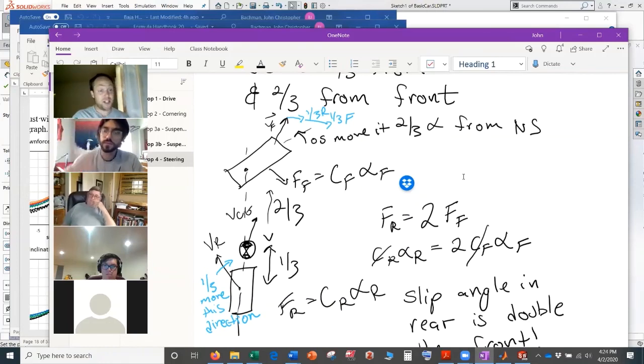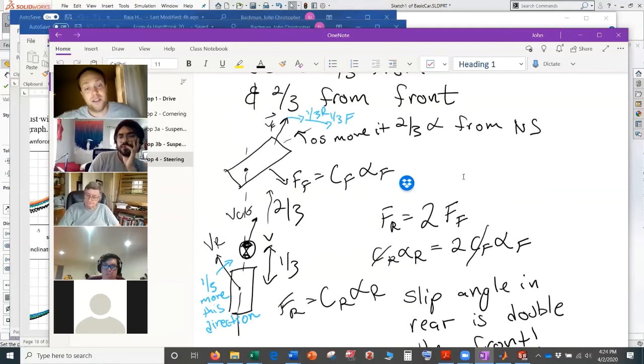So imagine the frustration you have when you think you're on this line, turning in around, and you keep going further and further in. So you're having to fight it back out of the turn, basically, right? That's why you hear the drivers talk about it. It's a totally dynamic effect, but it happens anytime you have this oversteering issue, anytime your front has more ability to have traction than the rear does. This will also happen when your CG is further in the back.